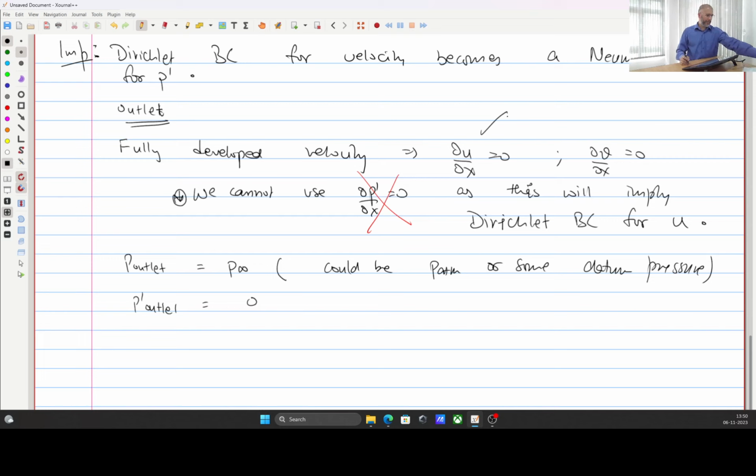I think that's it. I just need to give you an algorithm, but that is simply a summary of what we have written till now. That can be given in the next class, and that will end our discussion on the semi-explicit method for solving fluid flow equations using primitive variables, that is U, V and P. In the next lecture, we will start with semi-implicit methods, and a very common scheme called SIMPLE. That was given by Patankar.